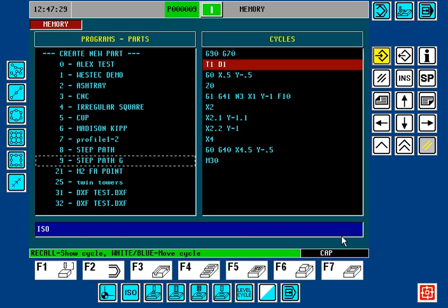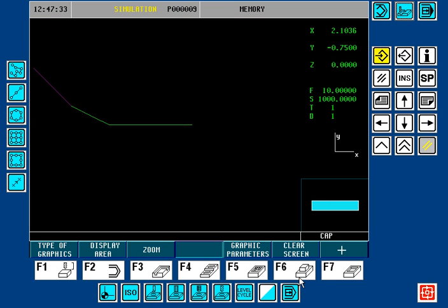Let's run this now in the graphics simulator with 3-block look ahead. Here the project completed itself, and it skipped the small step by shooting right past it because I've given it a 3-block look ahead. So it looked in the tool path, saw that it cannot physically go down inside the small step, so it went over it.